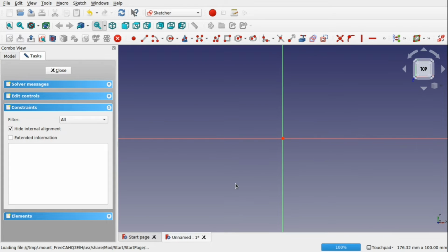Now when you're using this, we must anchor it against something in our sketch, because there's certain boundaries we mustn't go past, and you'll be using the construction geometry or a separate sketch to create those boundaries. What I'm going to do here is create a line, a curve, a B-spline, any type of geometry, even if it's closed like a square or a rectangle in there. It doesn't matter which it is. This will have an effect on that curve. These all can be manipulated by this hybrid curve.